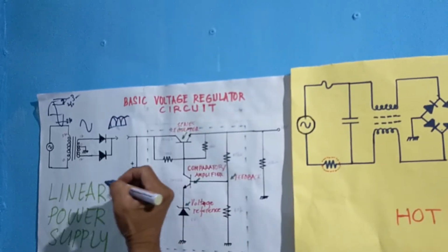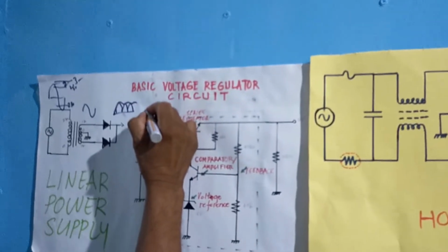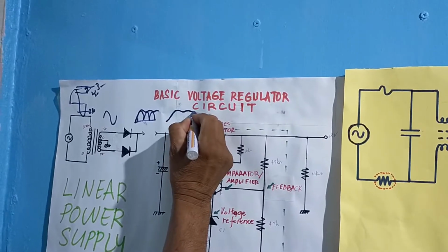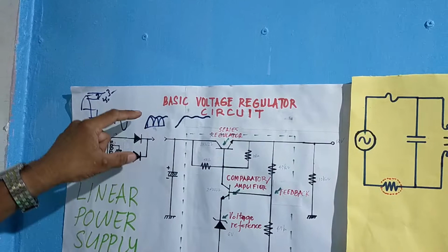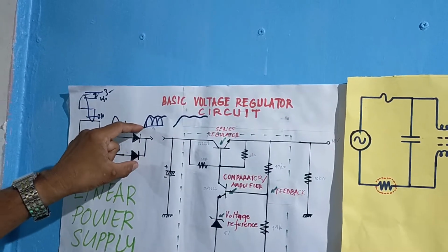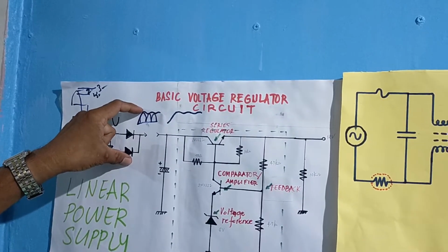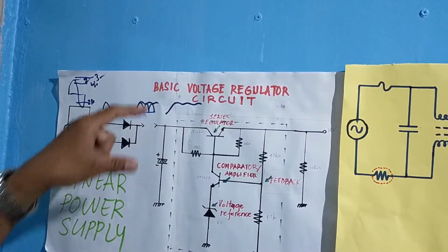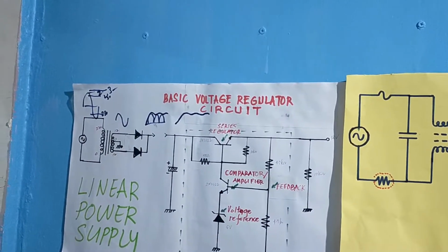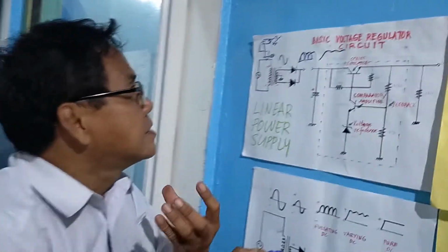So the output across capacitor goes like this. So the variation now is smoothed out. A while ago, at the output of the rectifier, it is 12, 8, 12, 8. A matter of 4 volts variation. It is a louder hum that you can hear.